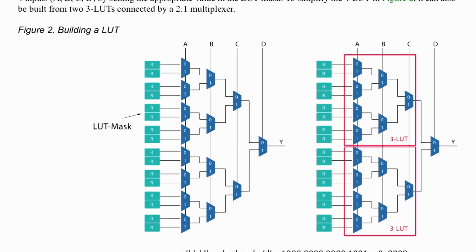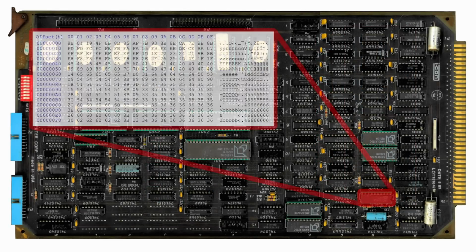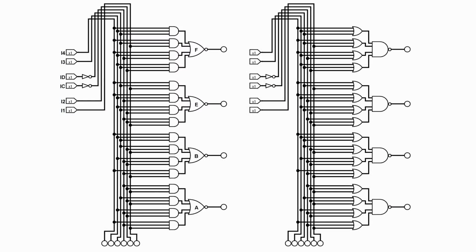This is actually a technique that's used a lot on the Centurion. They use a little PROM that is a lookup table for some swath of logic. And I believe that's the same thing that they did here. They just used a bunch of diodes to make a lookup table.